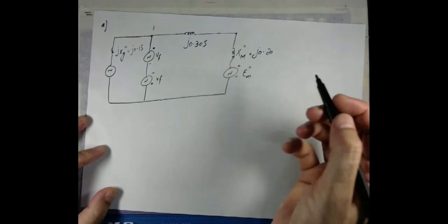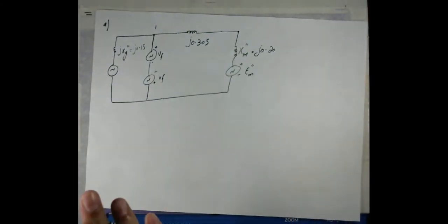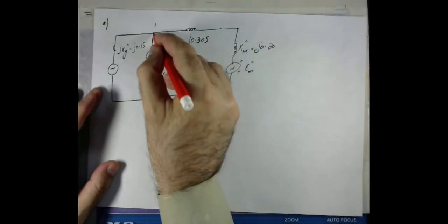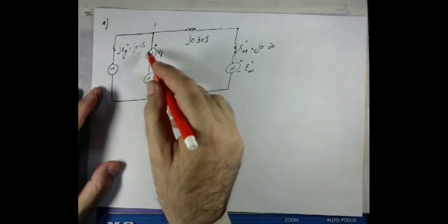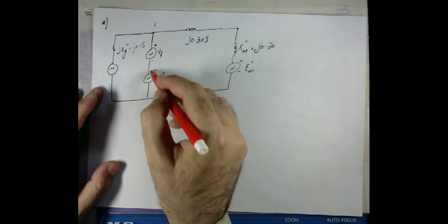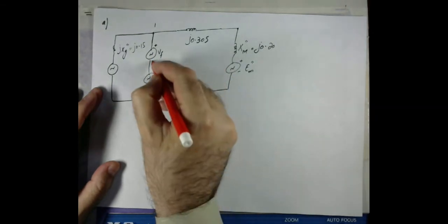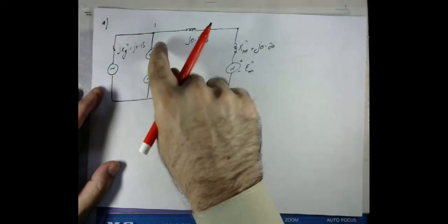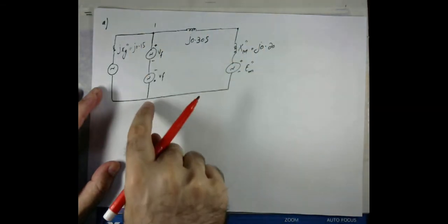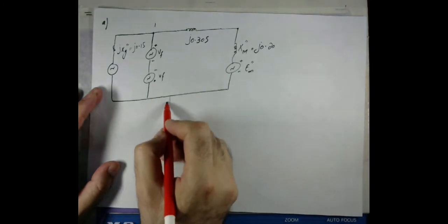Now this circuit basically represents the short circuit fault appearing at bus number 1, because the short circuit is represented by two opposing voltage sources, minus, minus, plus. It means that it is a bolted type fault where this will be directly connected to the ground. So let's say that is the ground.